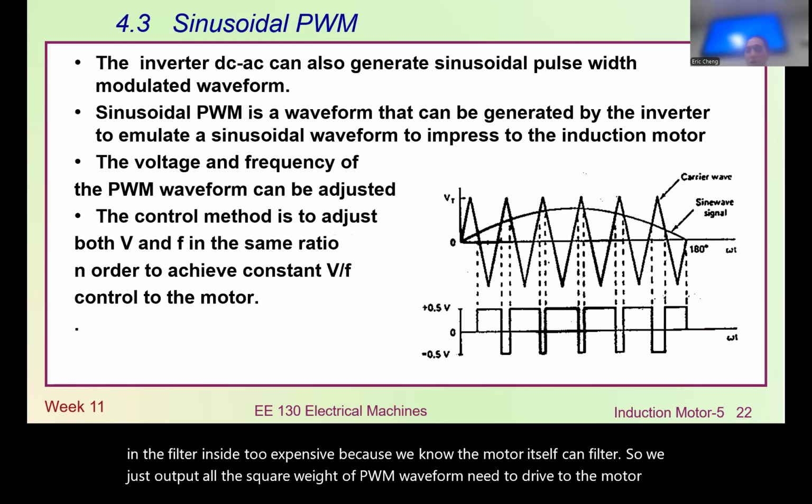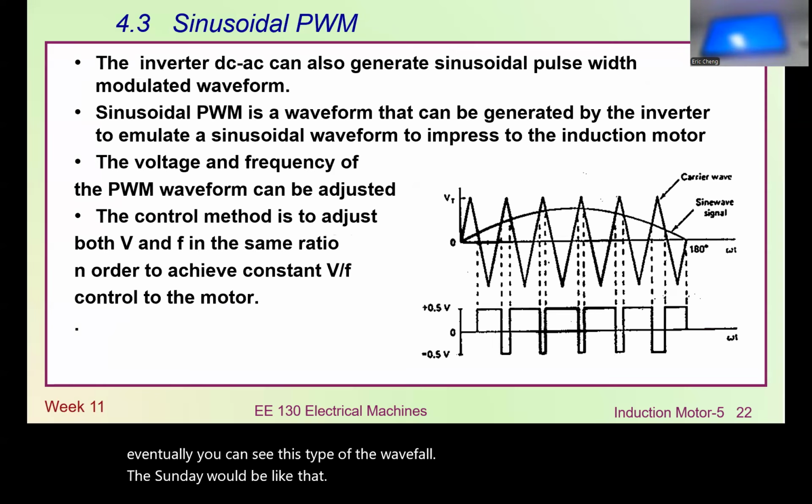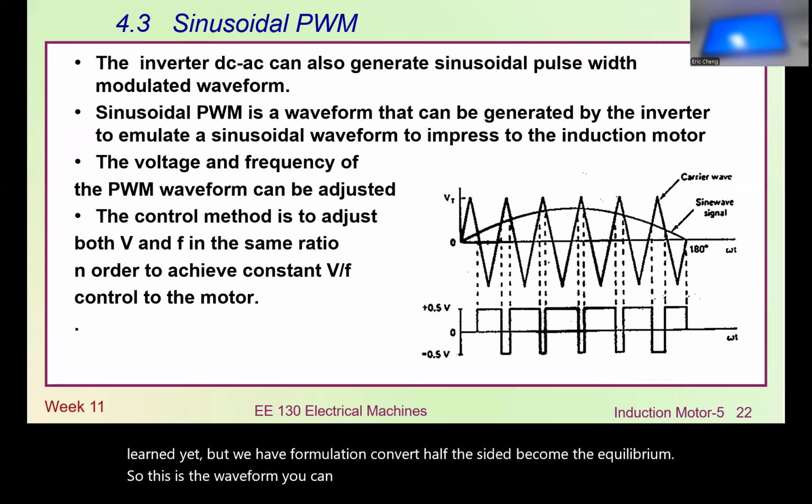So eventually, you can see this kind of waveform. The sine wave will be like that. But actually, for the sine wave, you can have some formulation. I think you haven't learned it, but we have a formulation to convert half the sine wave into the equivalent PWM. So this waveform, you can see, still looks like a sine wave. There's more pulse width. So this looks like a sine wave. So this waveform will represent a sine wave applied to the induction motor.